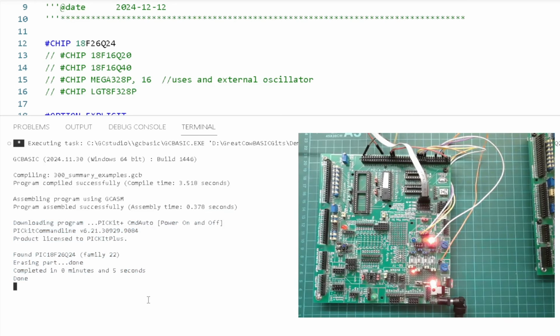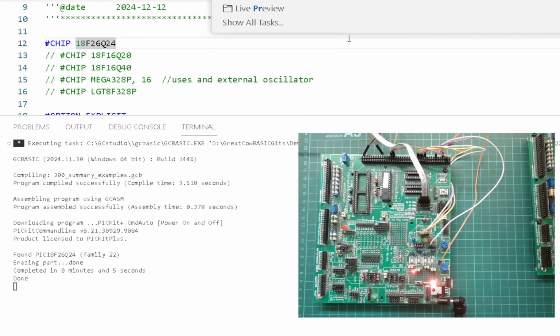If you want to generate a file that can go into MPLAB for debugging, because this chip cannot go into the old debuggers, it has to be MPLAB-X, you have to make a change, and you have to use PIC-AS. To get to PIC-AS, you already know how to do that. It's function key F4 into the Preferences editor.